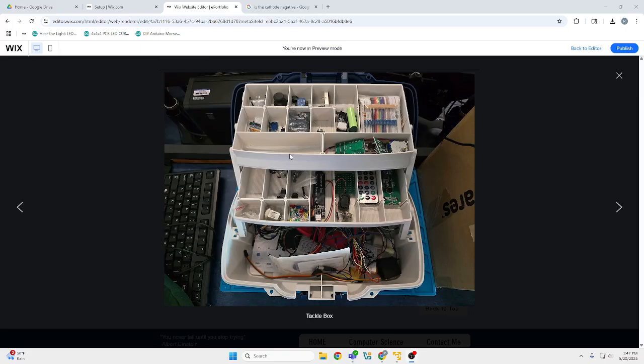This would then allow us to apply resistors, which we calibrated with this device right down here, where we'd connect the two prongs to each side of the resistor and made sure that the resistance was exactly how we needed it. It does this by measuring the voltage, sending a current in, and completing the circuit within the device, and it's actually pretty cool. All the resistors were up here in our tackle box of things.